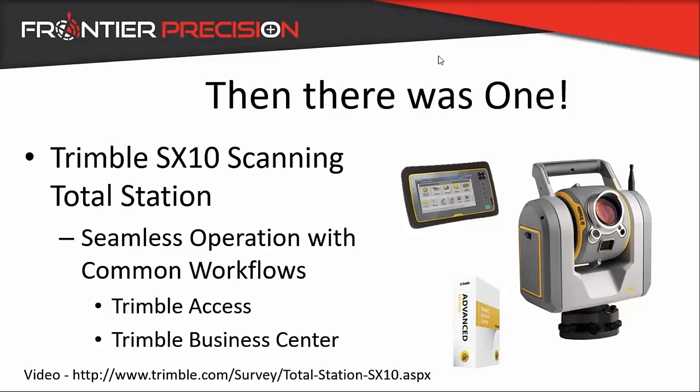Okay, is a traditional collector required to run these, or are they mobile device capable now? So right now the SX10 is supported by Trimble Access and Trimble Access on a tablet. So you have to be running a Trimble tablet to run the SX10. So to answer the question directly, traditional iPads and Android devices are not supported yet.